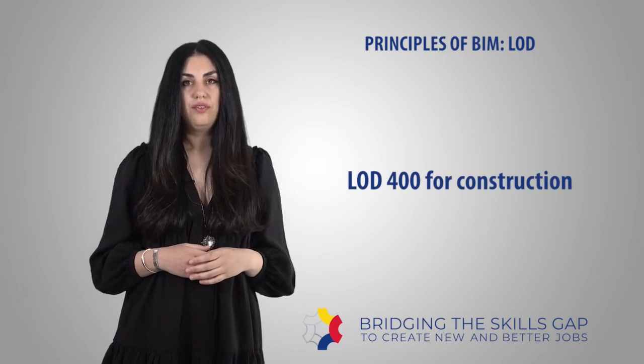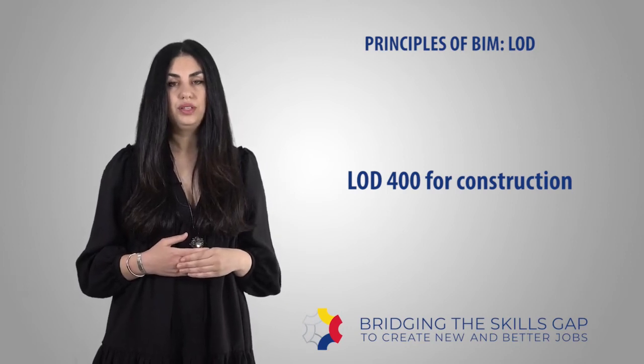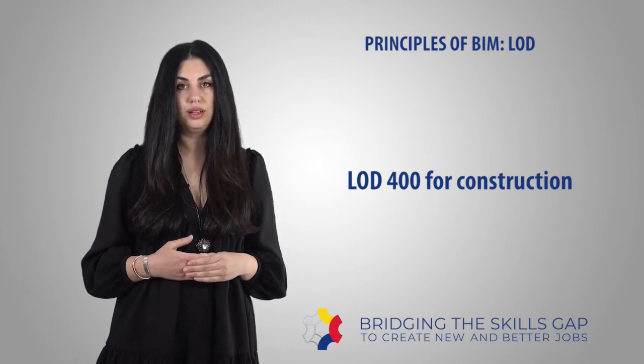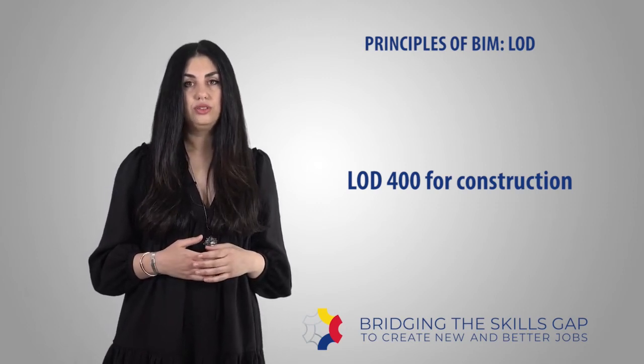LOD 400, fabrication and assembly. Model elements are modeled as specific assemblies with complete fabrication, assembly, and detailing information, in addition to precise quantity, size, shape, location, and orientation. Non-geometric information can also be attached to the model elements.